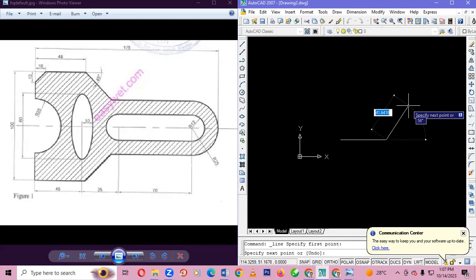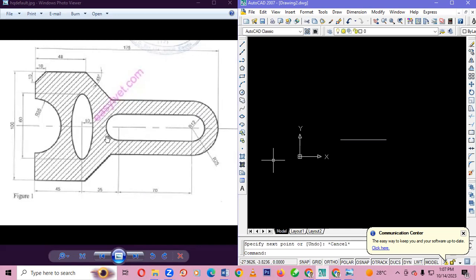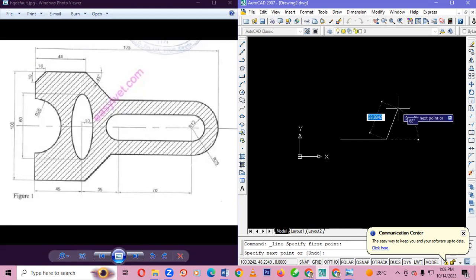So remember, before we draw even this line, when you are moving straight, it is 180 degrees. But when you go up, it becomes 45. When you move from 45, you go to 90, then 135. So remember, the line has been extracted to form what we call 45 degrees. So that's why we come and click here, then you put here, then you can draw 20, tab, 45 degrees, like that. So that's how you'll be able to draw the line.